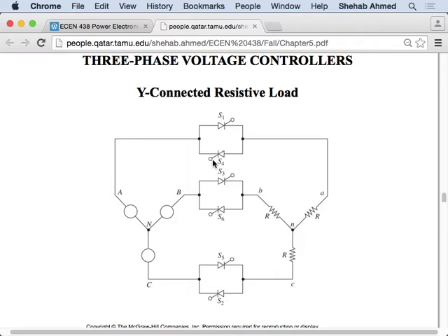But if you put three-phase unbalanced voltages in that box, you will get three-phase balanced voltages rotating in the same fashion as your input. You will also get three-phase balanced voltages rotating in the opposite fashion. I know we spent a lot of time on this in 459, but basically, if you have three-phase waveforms that are not balanced, then the theory that we talked about, the three-phase balanced circuits from last time, we cannot apply.